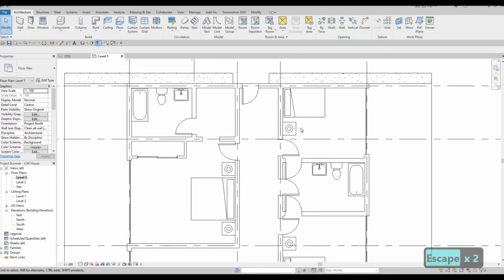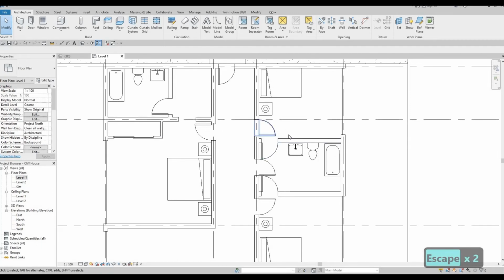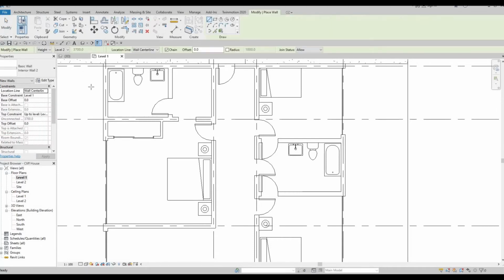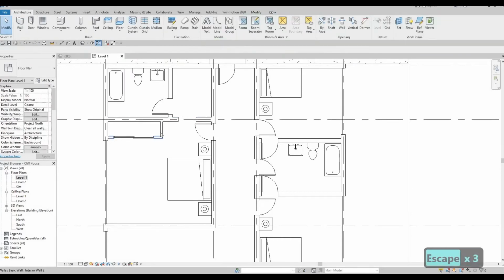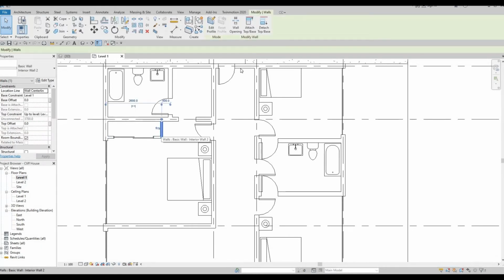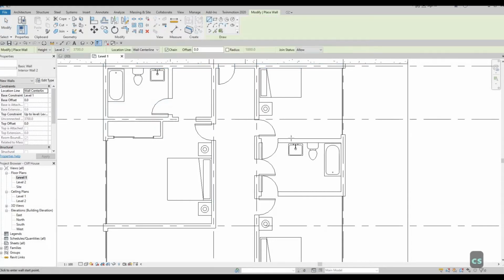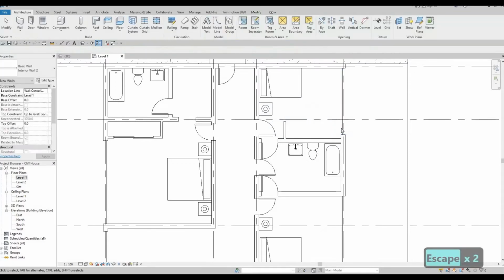And then let's add closet in this space as well. So click on wall again, or we could actually just click on the wall interior number 2 and click on CS or create similar. That's the fastest way. If you know that you already have the certain kind of wall or object, you could just keep on adding it like so. So here we have a dilemma.